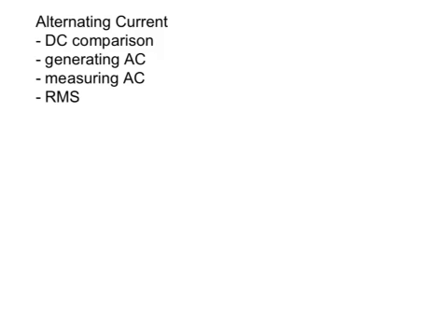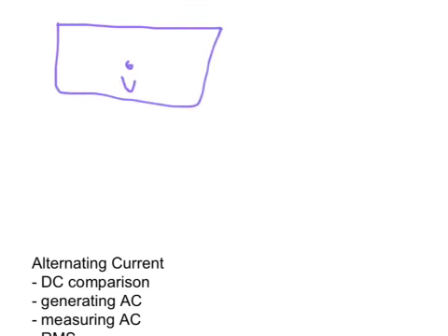If you were to stick an analog voltmeter, that's one of these ones with the needle that moves, that would shift back and forward for your alternating current. If you had your zero somewhere in the middle, then it would shift back and forward either side of that.